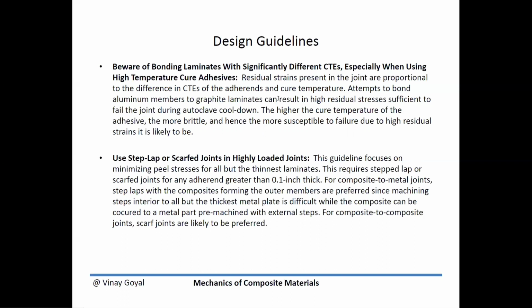We also want to use step lap or scarf joints in highly loaded joints. So feel free to pause the video, search these terms and see if you can find them in the literature. But the bottom line is that these type of joints can also minimize peel stresses. And so they are good design practice.